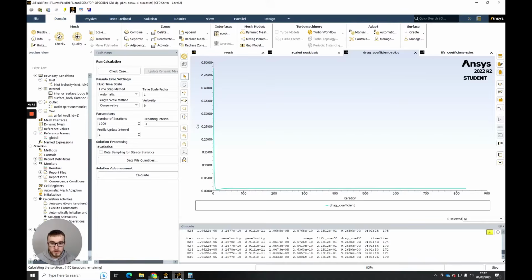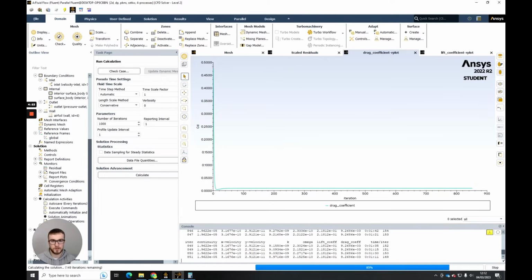And then the beauty of CFD is that once we know our simulations are accurately represented in reality for this case, we should expect to change flow conditions and still get accurate results. So I should be able to change the velocity to 44, 43, down to 40, and for the most part I should be confident in my results that I'm representing reality properly. Doing an experiment, for example, might not always be available to change quantities or the geometry that easily. So this is why we use CFD, and this is why it's valuable.